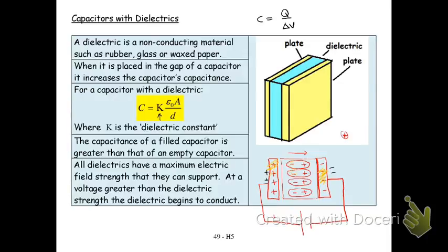And you're getting free capacitance. It's like you put a piece of paper inside and you're getting a better capacitor out of it. And what's more, you can use the paper as a gap creator. Trying to get 2 parallel plates that are not touching is incredibly hard. So put a piece of paper between them and roll them up, and you have a really nice capacitor. It's brilliant, really. It works really well.